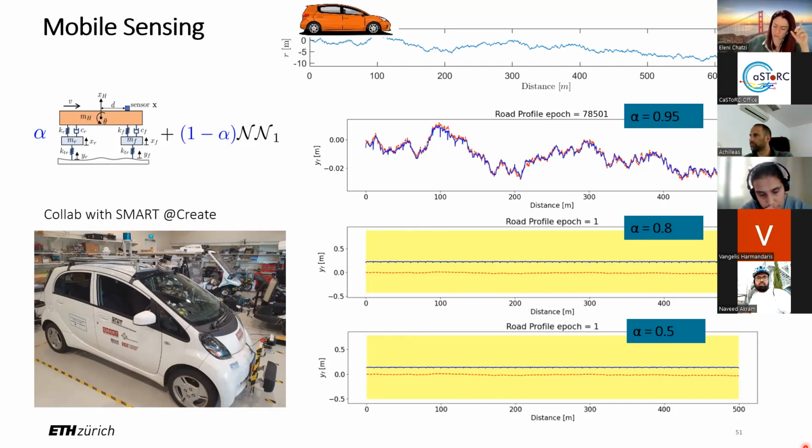It should not be a vibration-based monitoring of accelerations or strains that are dynamic, but more of a monitoring that relies on the propagation of waves. So we have a separate tool that we use in that case. It's more called non-destructive evaluation, and it's basically a guided wave-based approach for understanding the nucleation and growth of smaller flaws like cracks. And in that case, we're using higher frequency ranges. We use repetitive pulses that are propagated through a medium, and we try to also use a network of sensors that are receivers of those waves, and where the analysis then becomes an analysis of a wave propagation phenomenon, less so an analysis of modal or vibration. So my point is not only the method, but even the monitoring tool has to change when you're interested in such phenomena.